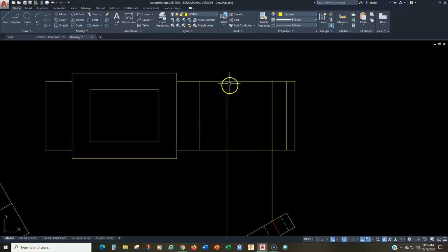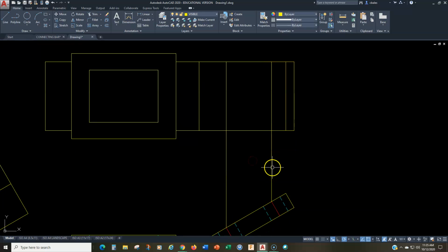So when I want to lay out the center of where these holes are, I projected these up, but I'm just going to offset these by the regular dimension, which is 12 and 26. So offset 12 and offset 26. That little grid is where these holes are going to be positioned.